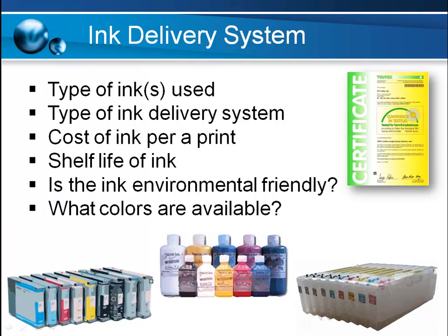You also want to look at what's the shelf life of the ink. Most CMYK inks typically will last a year or maybe less. A lot of the white inks have a shorter lifespan, could be 6 months or even less. So understanding what your shelf life is on the ink, what do you have to do with that ink while it's actually on your shelf? Especially with the white ink, the ink has the ability to separate. You want to make sure that the pigments or the titanium dioxide that's actually in the ink stays in suspension.